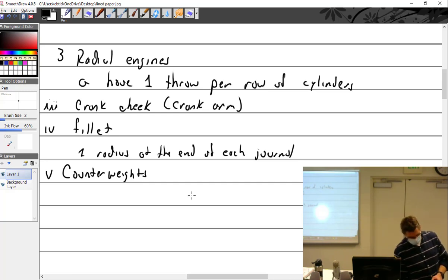Well, there were some problems with them not being hardened and nitrided properly. And these plates here, they're a press fit. Not by much. You just put them in there and tap them with a little hammer and a punch and they just kind of pop in. They're not real tight. There were some nitriding problems and just enough movement that these started moving. They kind of worked their way out here. And then once one of these pins comes loose, and this crankshaft is turning very quickly inside of the engine, once these come undone, they start beating the crap out of the crankcase. But the good news is it only does it for about a minute or two, and then it sort of self-corrects and stops working.